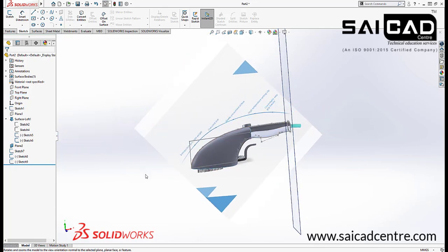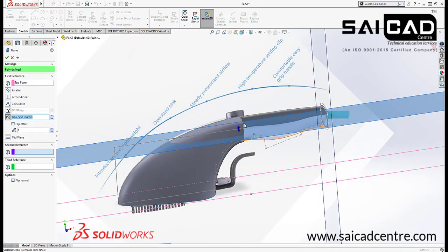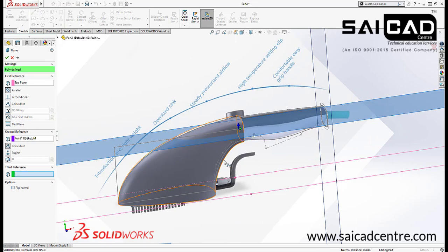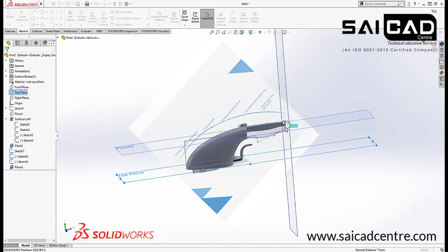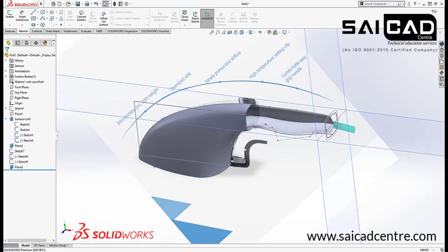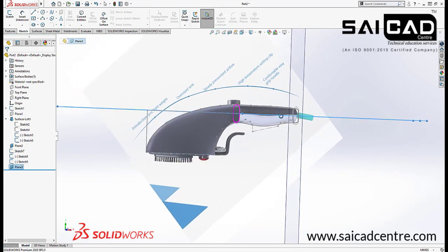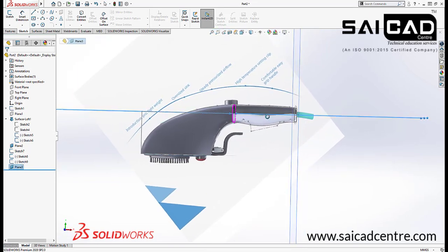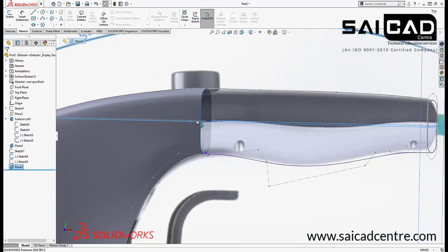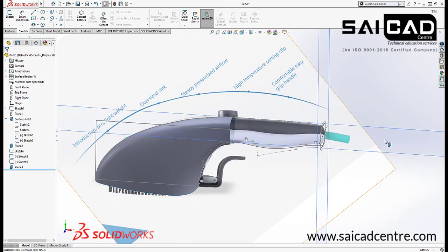Okay, so select the top, press the control and drag that in upside and select a point, and we have the object. And now I can just create a spline right here, but remember that it should be in the center. So we know that I have created this in the center, so if I create something here, that will be again in the center. So go to the sketch,